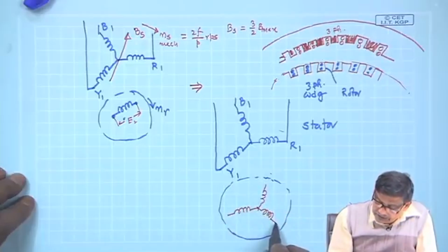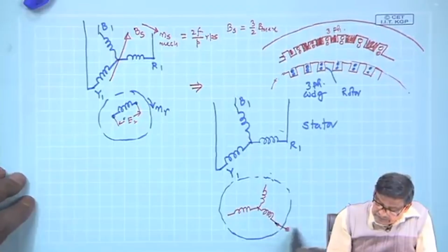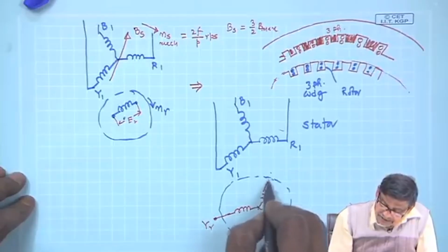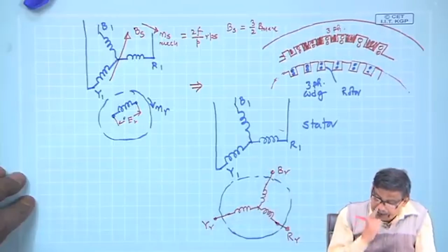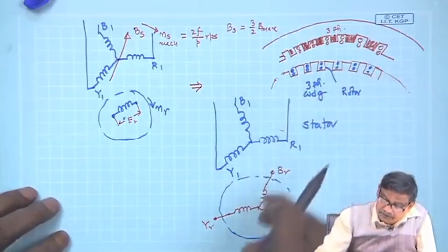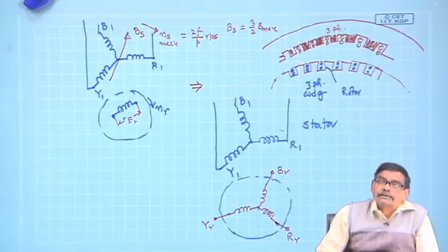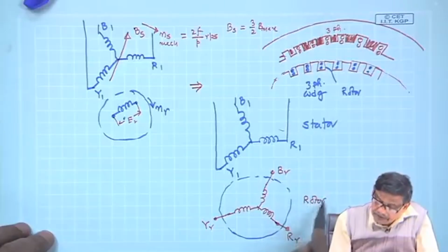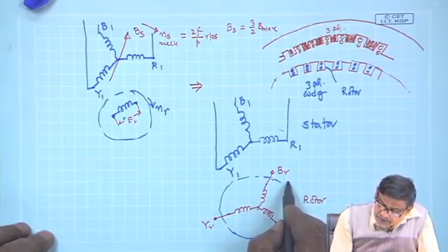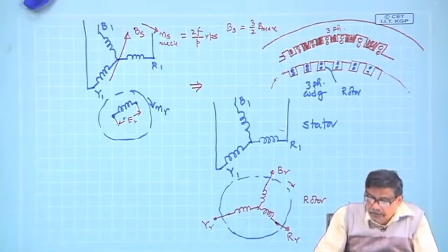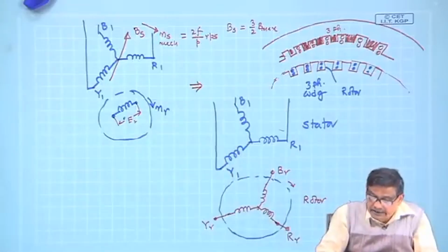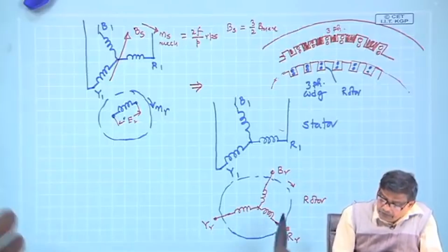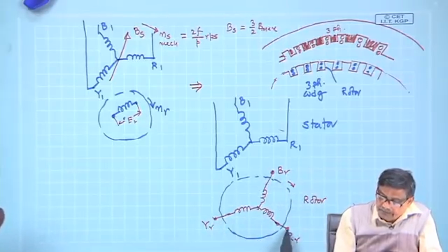And suppose this rotor terminals, this let me call RR, this is YR and this is BR, like this. So, this is the rotor 3-phase winding, which is also balanced and 3-phase type. So, this is the rotor part, and it can be rotated externally or maybe it will rotate on its own when you energize the stator, we will see that. But the point is that suppose the rotor terminals are kept open circuited, what is going to happen?